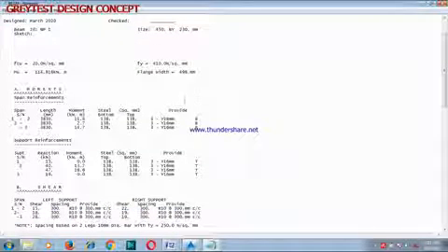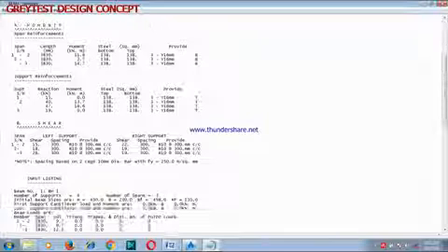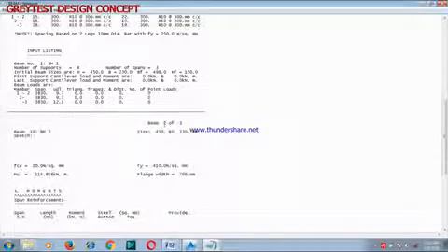Okay, characteristic strength of concrete, characteristic strength of steel. These are flange width. Now for bottom bars, look at 3Y16, 3Y16, 3Y16. This is our top bar, 3Y16, 3Y16. Okay, for beam 2.